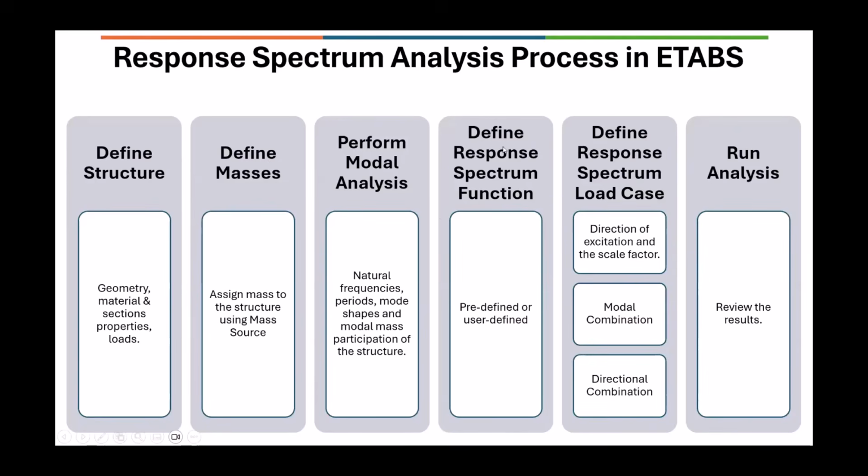So that will be stage two. In stage two, we'll be defining the response spectrum function. It can be a predefined function based on the codes, or user defined in case of any site-specific response spectra that you want to use. So the program has both the options.